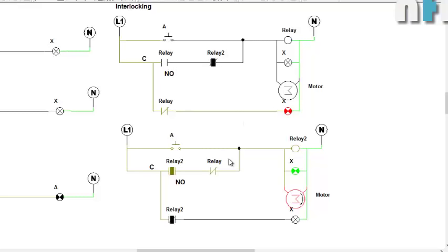So I'll go back here now. This is on, so this is open. This is latched because this is closed because this is off. So when I press this switch, now again this will get on and this will get open. So this motor will be unlatched. See, similarly for that again. So this thing is called interlocking.